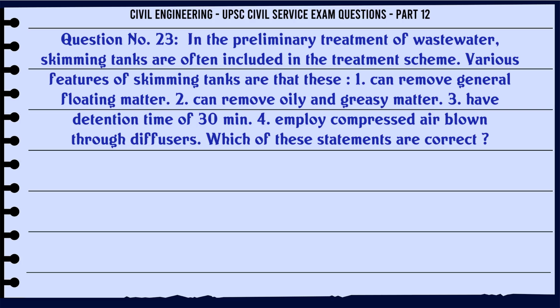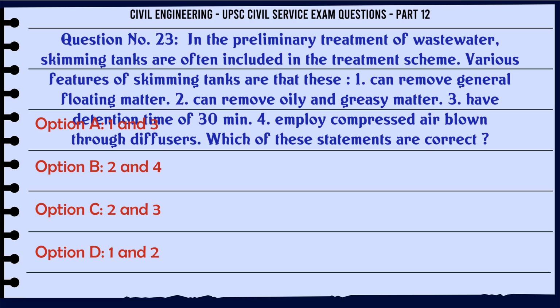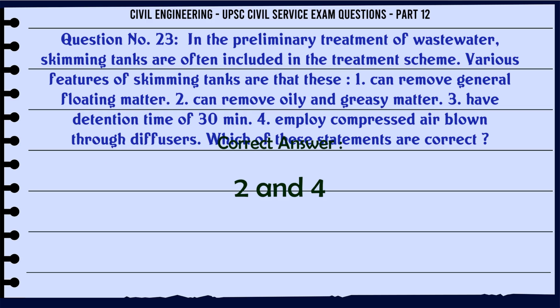In the preliminary treatment of wastewater, skimming tanks are often included in the treatment scheme. Various features of skimming tanks are that these: 1. can remove general floating matter, 2. can remove oily and greasy matter, 3. have detention time of 30 min, 4. employ compressed air blown through diffusers. Which of these statements are correct? A. 1 and 3, B. 2 and 4, C. 2 and 3, D. 1 and 2. The correct answer is 2 and 4.